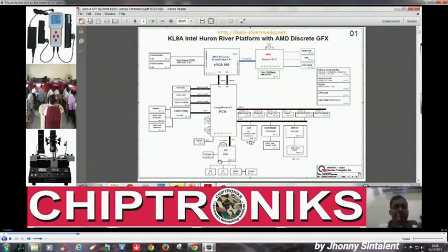If you get that just by seeing the notebook motherboard, then you can repair it very easily, and all that is the exact power sequence. You don't have to go into the schematic and try to find where my power sequence is. No, you can tell it by seeing the PCH, by seeing the ICH. You can tell by seeing this chipset, right?